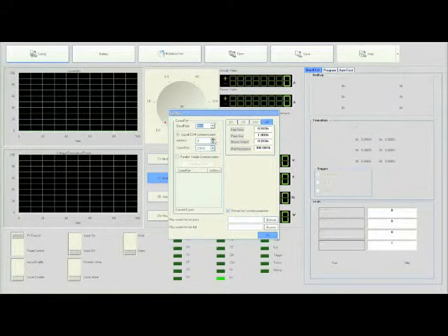If a USB adapter is used, Windows will automatically assign a COM number for the USB virtual COM port. This can be verified inside Device Manager under Control Panel settings of your operating system. Once verified, click OK to close the config window.